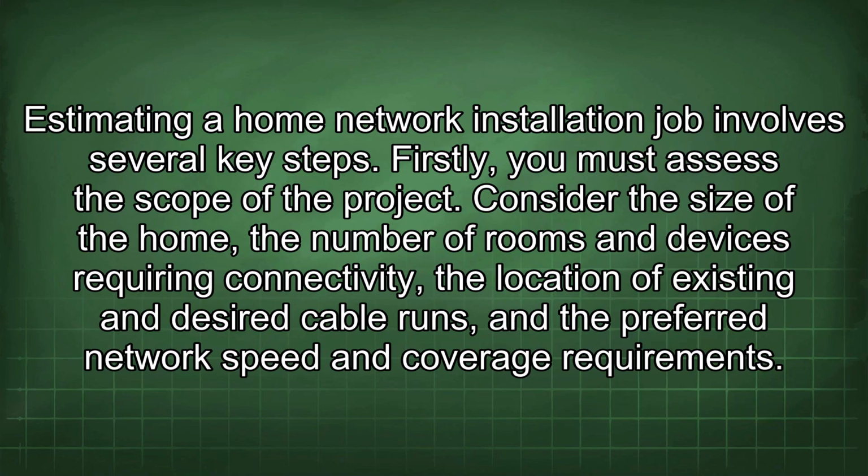Estimating a home network installation job involves several key steps. Firstly, you must assess the scope of the project. Consider the size of the home, the number of rooms and devices requiring connectivity, the location of existing and desired cable runs, and the preferred network speed and coverage requirements.